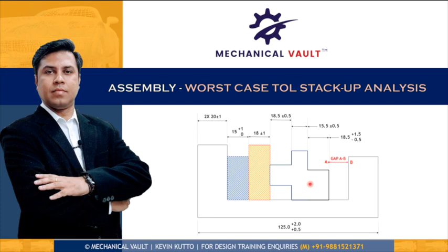In mass production, we cannot manufacture any part dimension with zero variation. That means every dimension on the part must be allowed to vary within the given allowable tolerance, and yet we must meet the given function of the part. Now the function could be required clearance or required interference or required overlap, or just to ensure the parts assemble readily with each other in the worst case.